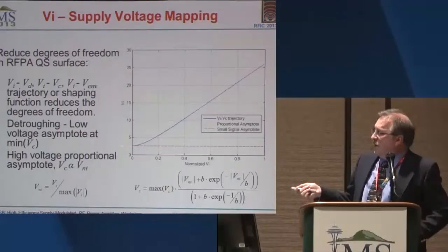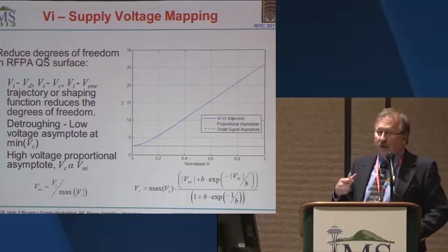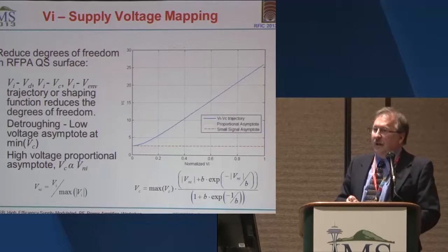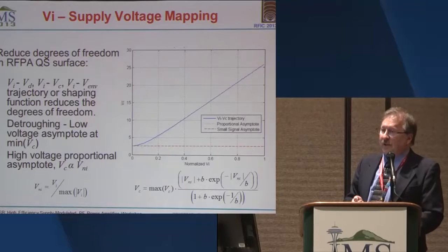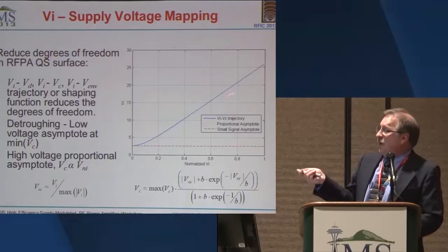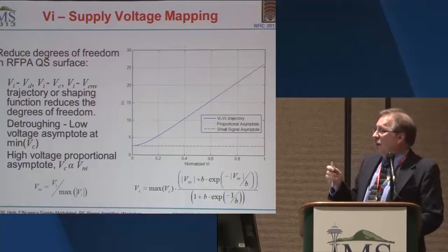We typically clip it off at a low value here that still has sufficient gain that we don't have complete gain collapse and complete shutdown of the PA. The PA doesn't really like it to be taken down to 0 voltage, so we don't like to put it there. But I do like to have a smooth transition to that fixed value down there at the low end.